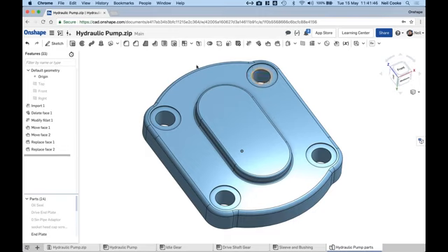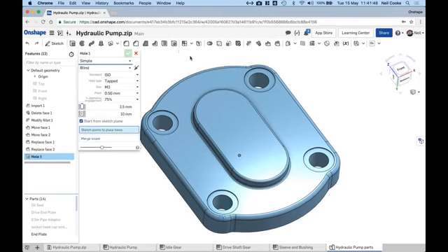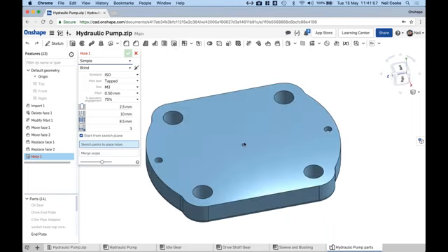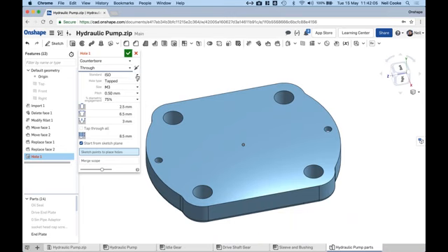Another question, does Onshape have the equivalent of a SolidWorks Hole Wizard? Yes, we do. So when you use the hole feature, all it's looking for is a point to place it on, which could be the origin. Sorry, looking for a sketch point. So you can specify whether it's a simple counterbore, whether it's a through hole, whether it's ISO or ANSI, tapped, what size you want it, M16, and then it's going to automatically select all the correct data for you and apply that to that hole. And then when you create a drawing, there will be a hole callout and it will show the tapped feature in the drawing as well. Okay.